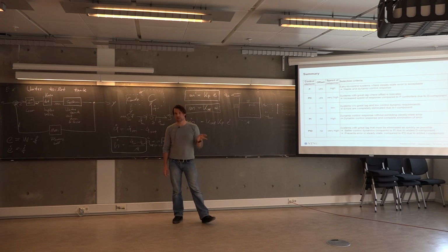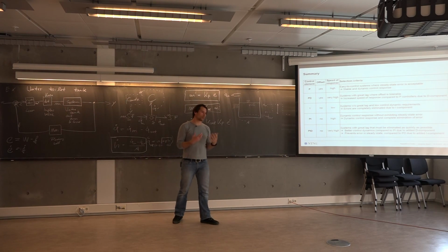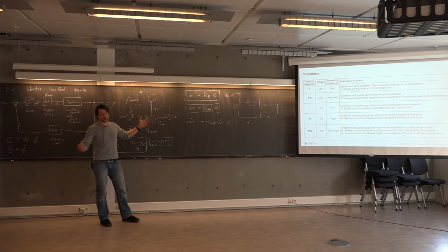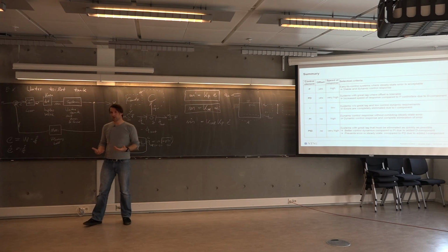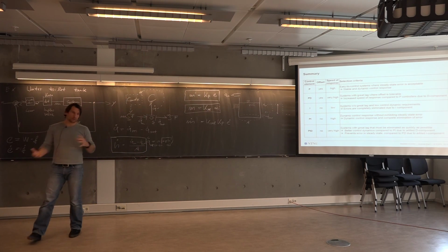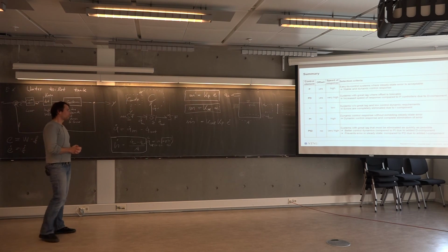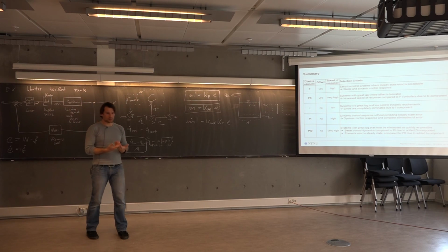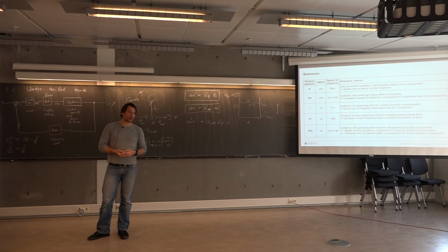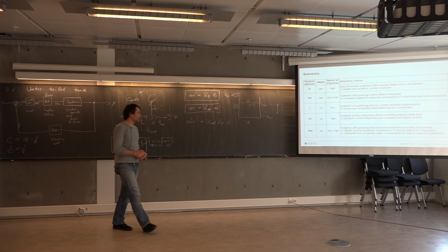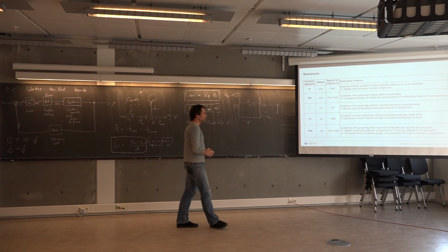And it also depends on the system that you want to control. If there are large storage elements in the system, meaning in our case, if the reservoir is large and if there's large inertia involved and the inflow and outflow rates are large, or the rates of change are large, in order to prevent damage due to high flow rates and high pressures, you might have to use some control concept which has a very fast response, right? In order to not end up with pressure peaks, for instance.